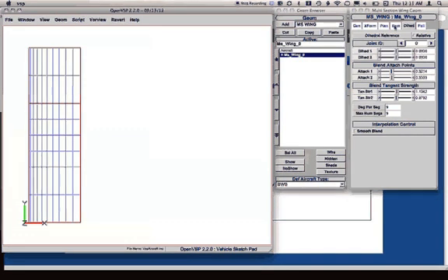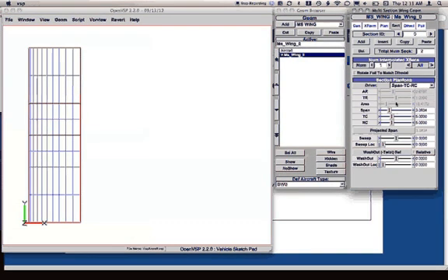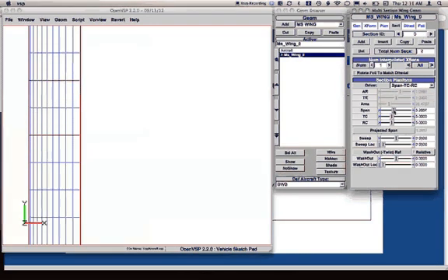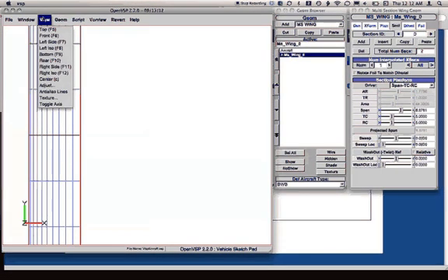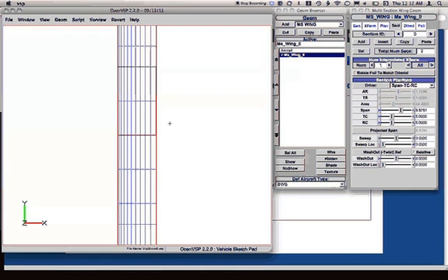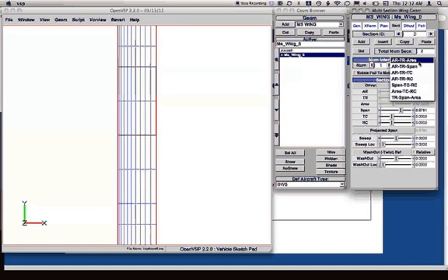Again, we're going to come back over here and say, we need to change the span. We need to make this larger. So notice how we have different options for linked. In the case of span, TC, and RC, we have the options to change these sections. But we don't have options to go through and change the other pieces as well: area, taper ratio, or aspect ratio. So we can come in here and choose one of these other sets of linked parameters.